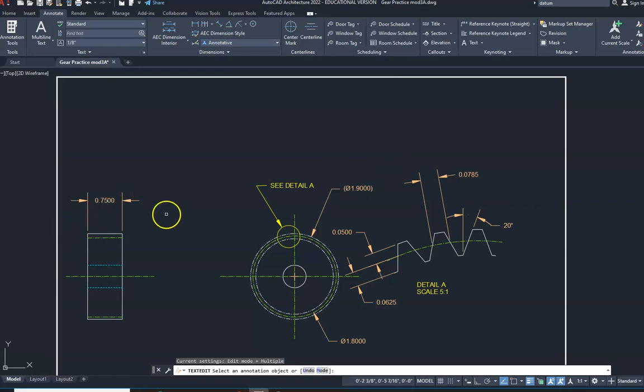So you can go back and view it again. I showed you how to do the basic dimensions with linear dimensions. There is the align dimensions here. There's angular dimensions. There are also align dimensions where we need to be very careful about our snaps to make sure that they snap in the correct location. And again, to move the dimension, all you have to do is make sure your command line is free, click, and then drag it where you want to go. Or you can also move the position of your text.